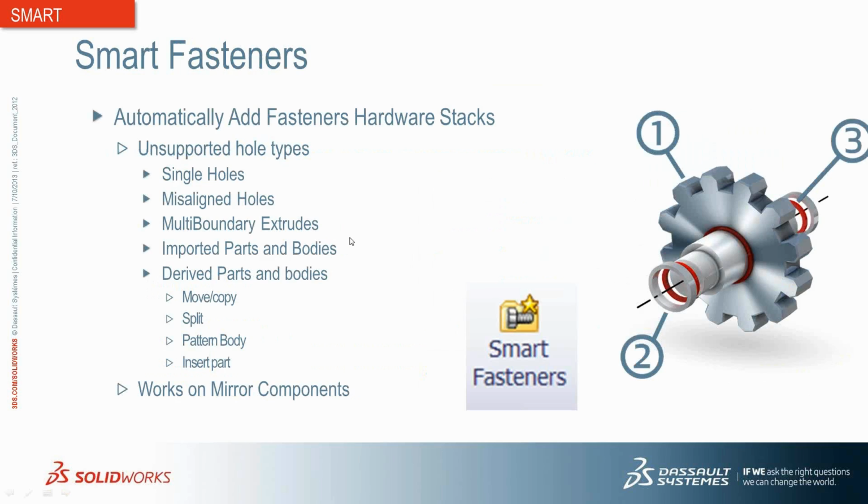Now this feature, Smart Fasteners, has more functionality in it than people give it credit for, but also has some kind of gotchas and nuances that you really need to be prepared for if you're going to utilize this. Well, Smart Fasteners does require you to have Toolbox, so you're going to need the Professional or the Premium package. But with Toolbox, we can automatically add fasteners and stacks to our assemblies.